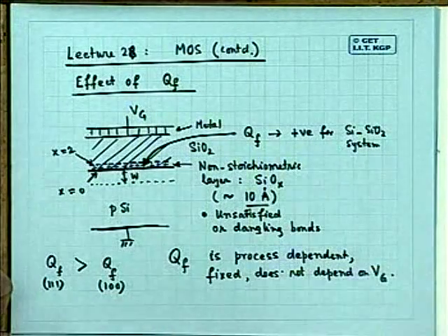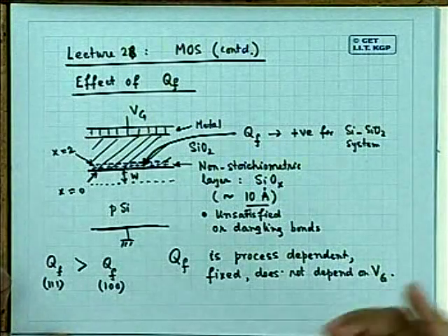And I think you know that in MOS inverters, all VLSI or MOS integrated circuits, the driver must be an enhancement mode device. Otherwise, there will be an input-output compatibility problem. The output of a MOS inverter should be able to drive another similar MOS inverter. That will not be possible if the driver is a depletion mode MOSFET. So from the application point of view, enhancement MOSFET was essential. Without an enhancement mode MOSFET, one cannot make a good circuit.